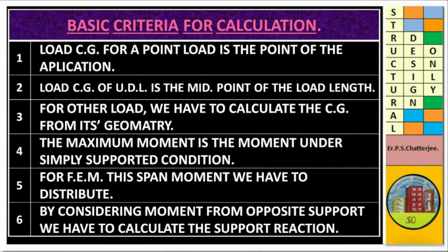Basic criteria for the calculation. Load CG for a point load is the point of the application. Load CG of UDL is the midpoint of the load length. For other loads, we have to calculate the CG from its geometry.